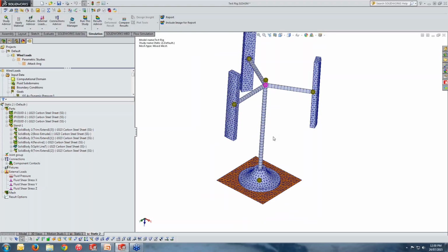One thing you might know very well when we're talking about 3 different element types, such as solid, shell, and beam elements, is that they have different degrees of freedom. Solid elements basically have 3 degrees of freedom. Well, the shell and beam, as they are 2D and 1D elements, have 6 degrees of freedom in order to mimic not just the translation, but also the rotation.